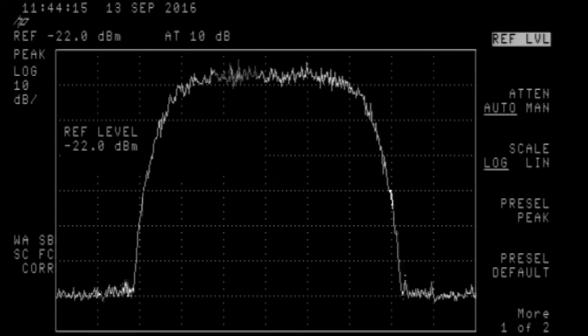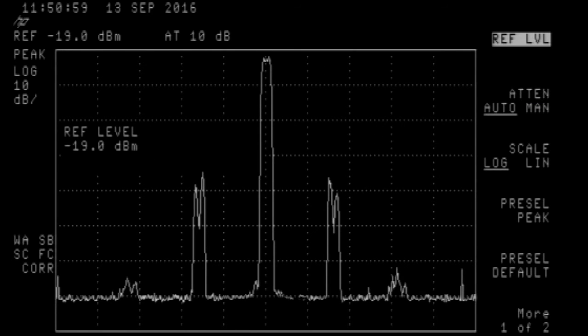That's it. Currently with DVB-S2 I haven't added all the required interpolators and filtering for the reduced bandwidth modes, so the picture above shows you why you shouldn't operate the software below 2 megasymbols at the moment. I'll do a comparison with DATV-BS software, which does actually have the correct filtering, so stand by.